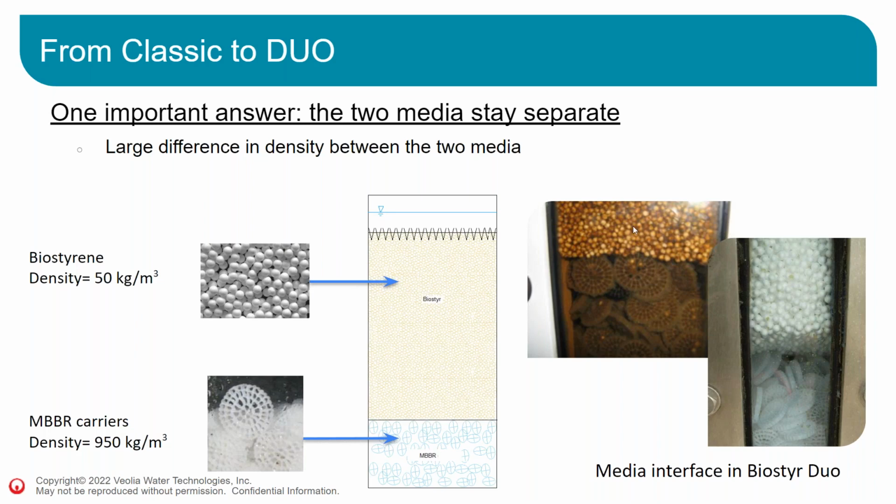And you have 2 pictures here, one from a pilot with clean water and one with a pilot that's been used for a couple of months, probably more than 1 year. You can see a couple of beads being stuck here and here, which show that the 2 media are in relation one with another. So there are some beads that might get stuck at some point when we go really aggressive on the backwashes. But the good thing is these beads are not progressing. There's not more and more beads. It's pretty stable over time, and it's not having any impact on the process efficiency.